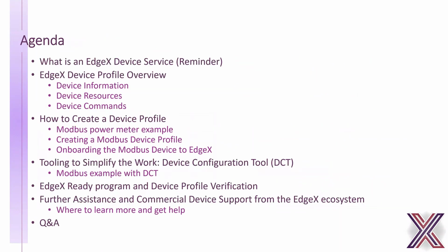So today's agenda is we're going to cover what is an EdgeX device service. We need to remind ourselves about that from last week. And then we'll jump straight into the device profiles. There's three main aspects to the device profile: device information, device resources, and device commands. I'm also going to be talking about creating a specific device profile. I'm going to use a Modbus power meter as an example.